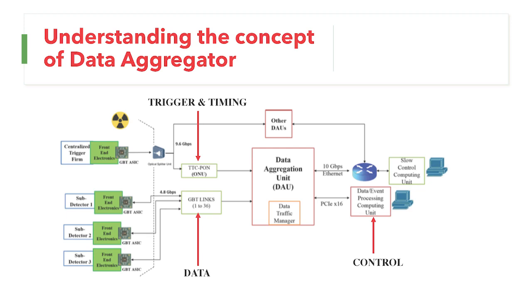Say, for example, stop the data acquisition immediately because the DAQ has gone down, or maybe the trigger or the detector has gone down, or maybe there is a beam dump happening. This control signal is asserted directly here, and you can directly take down the data flow. What this means for the DAQ is that the system is not jammed, and whatever bad data has been captured or processed, we can successfully drop.